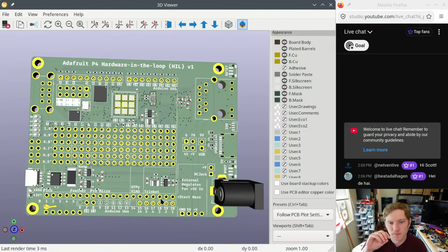I imagine that I will have to solder headers for the particular thing that I want to plug in. But I'm assuming I'm going to plug it in so I can pop the device under test off of it and on it. So I could do three that are Feather form factors, and if I need to, I could swap the device under test. And the USB, this here is designed for a double USB-A stacked connector. So in my first version at least, I'll solder that on. Same with this Ethernet jack. I don't care to pay them to do the hand soldering. I don't mind doing the hand soldering. In fact, for the barrel jack, I'll only solder the barrel jack on if I want to do that route.